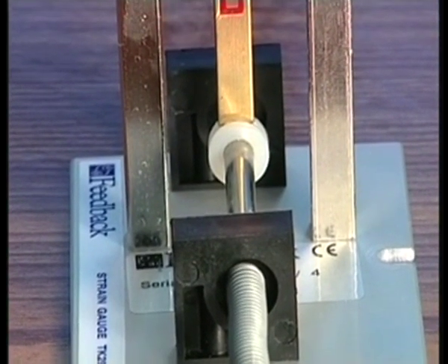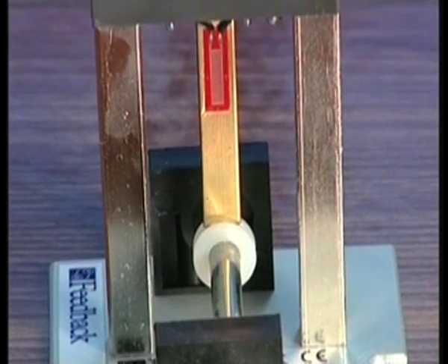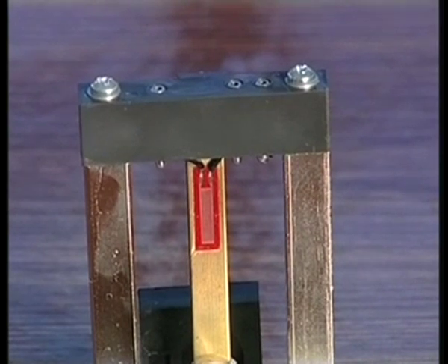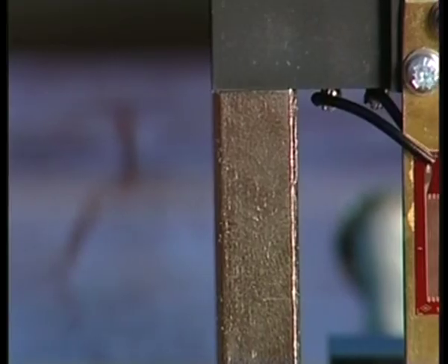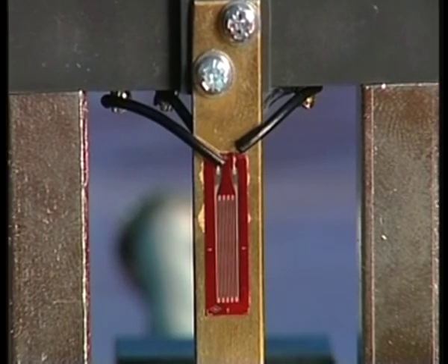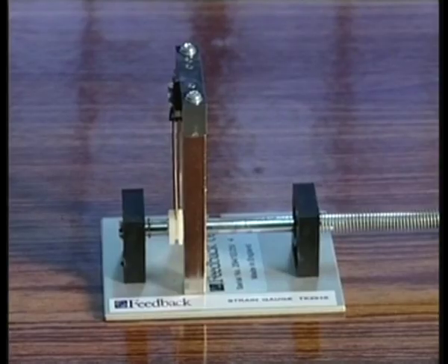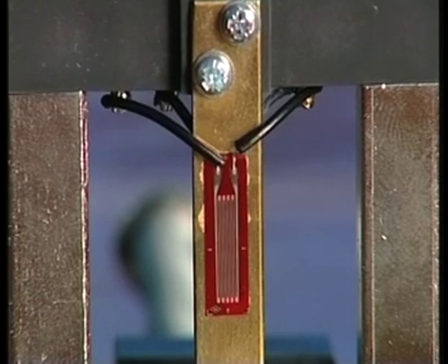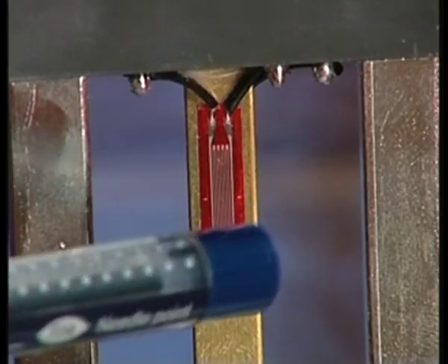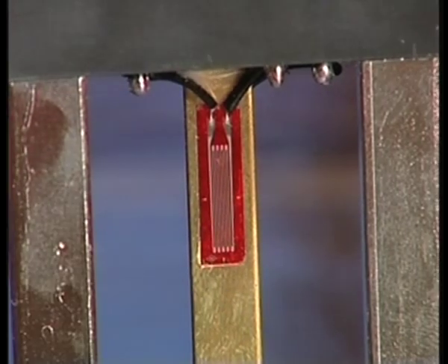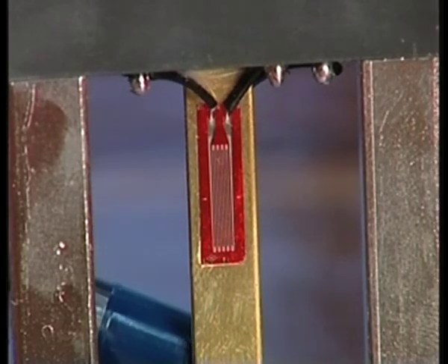In this displacement sensor, we have 2 strain gauges, one on axial elongation, the other on axial compression. If we put these 2 strain gauges on the opposite arms of the bridge, I will get larger output. You see here there is a strain gauge on this side, and there is another strain gauge on the back side of this brass plate.